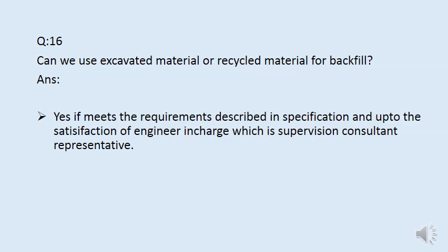Question number 16. Can we use excavated material or recycled material for the backfill? Yes, if it meets the requirements described in the specification and up to the satisfaction of the engineer in charge, who is the supervision consultant representative. Means that if the engineer from the consultant is satisfied and says that this material is within the range, then you can use the excavated material or recycled material. Next.